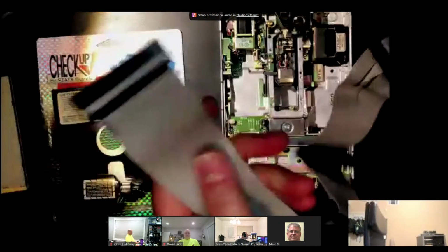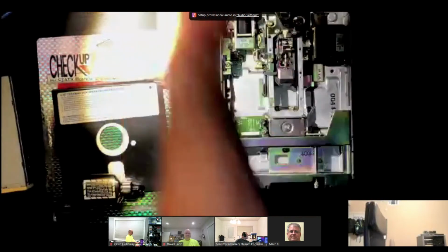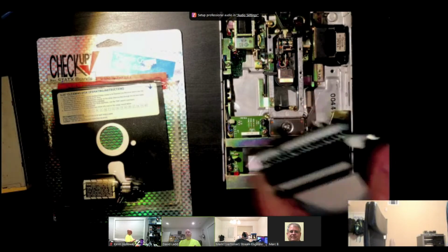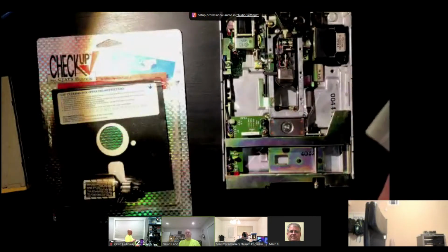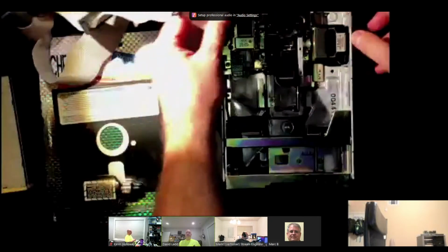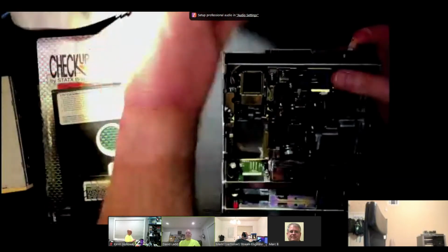So I can use the same cable for both, but is it possible to run the Greaseweazle in the Shugart style where you don't need to have the twist? In the case of the Greaseweazle that you have, Mike, which is the F1, drive select 0 and 1 are strapped together. So you don't even need a cable that has a twist.